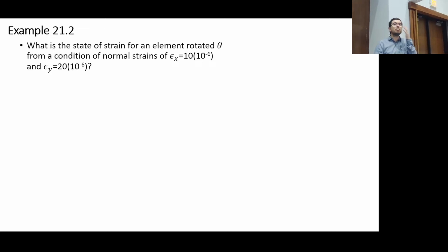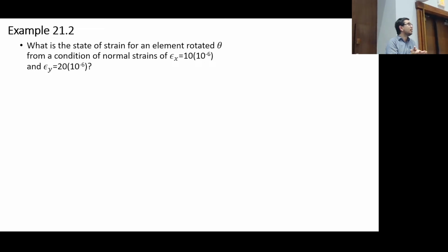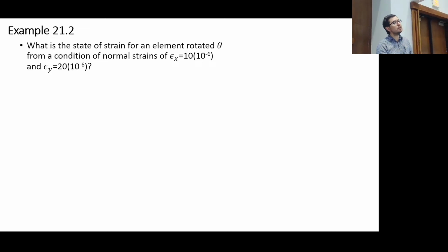So what would be a good problem? You caught me on the fly. I think a great exam problem, which is I think what you were getting at also, would be: here's the yield strength of the material. Tell me, what is the yield strain of the material?